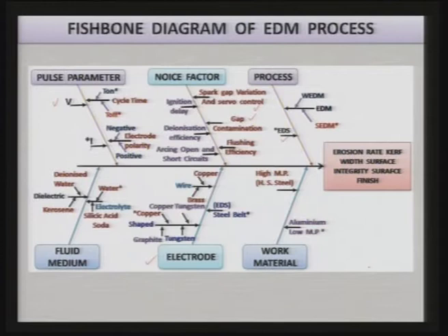Now, how are you going to evaluate the performance of the EDM process or wire EDM process? Then there is the erosion rate or material removal rate, characteristics of the kerf in case of wire EDM process, integrity of the finished surface.